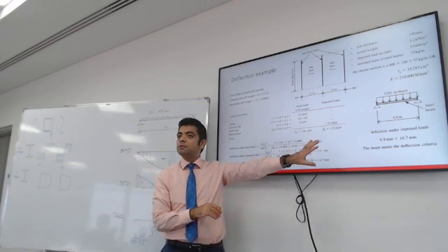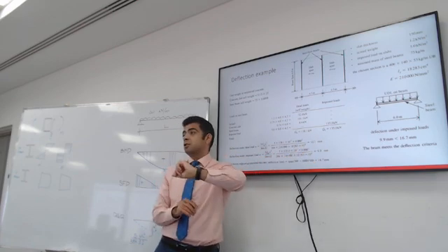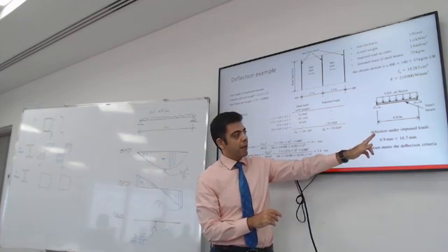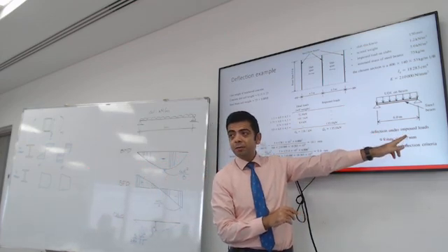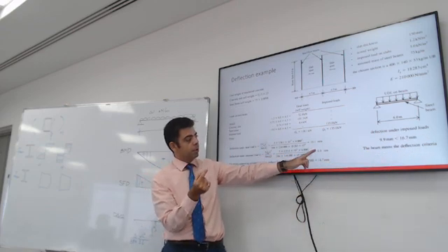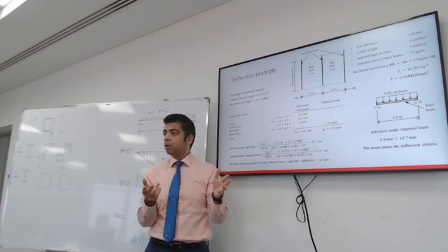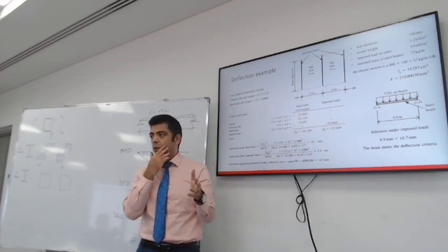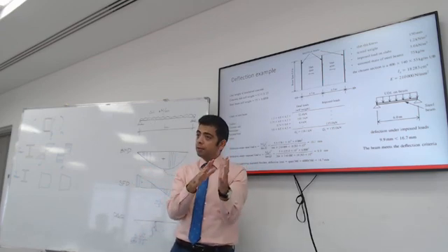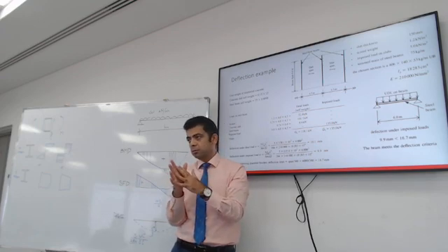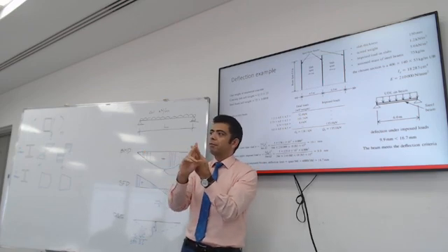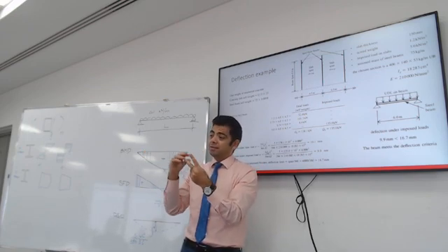This example is to check it against the Eurocode suggestions, and the Eurocode checks deflection under imposed or live load only. So do you limit the 9.9 millimeter or the 10 millimeter to the allowable limit? So do you make sure that the limit is not exceeded under live load or dead load? So we add them together. The Egyptian code would ask you to check both, live load only and live load plus dead.